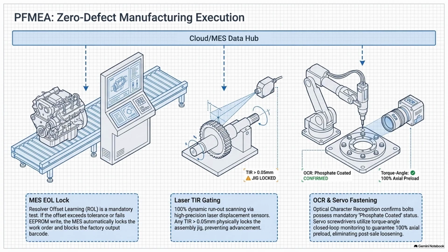During the R&D phase, engineers put the motor on a dyno and map out exactly how the motor's magnetic field distorts at every single possible combination of temperature, RPM, and current level. They bake that map into the LUT. I see. So in the real world, when you're towing that trailer up the mountain and the motor hits deep magnetic saturation, the software checks the table in real time. It sees the temperature, it sees the current load, and the table tells it, hey, under these exact conditions, physics dictates that the magnetic field is currently skewed by 1.8 degrees.